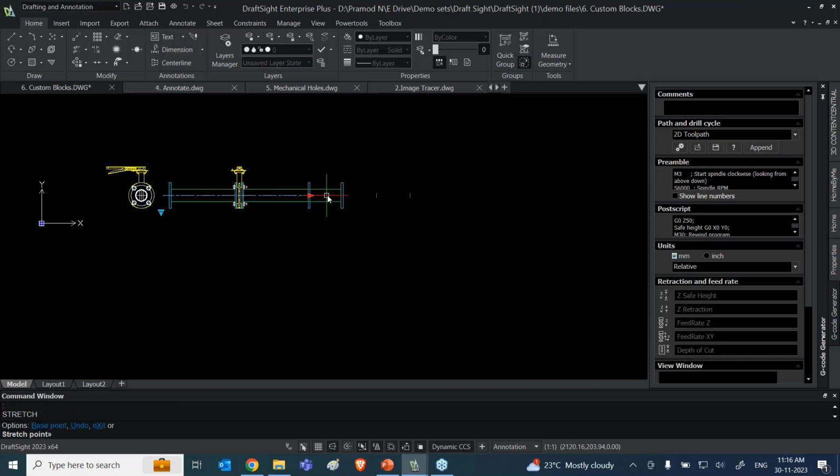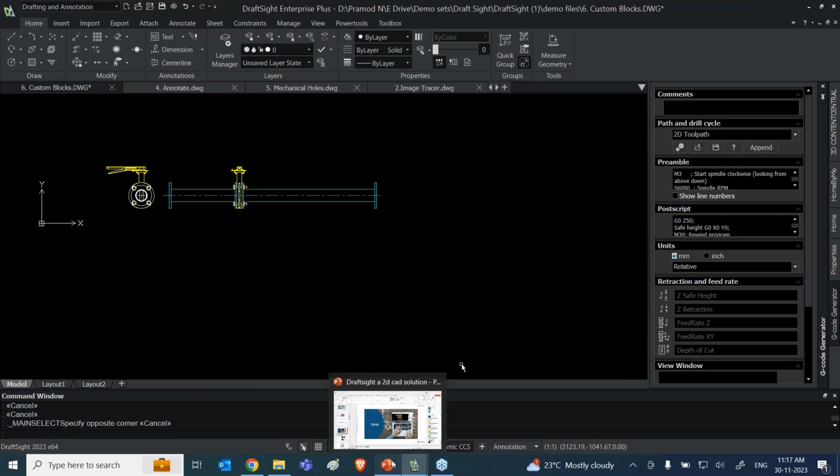And next, it's not only about creating different views but also about creating automated distancing. If you can see here, I have some lines that have been marked. People want to increase the distance with respect to only noted entities, or only some specific distance which works as a standard. In those scenarios, you can create one drawing and reuse it at different entities where you want similar drawings with different dimensions. This is where the dynamic block is very helpful for people who work on repetitive designs.